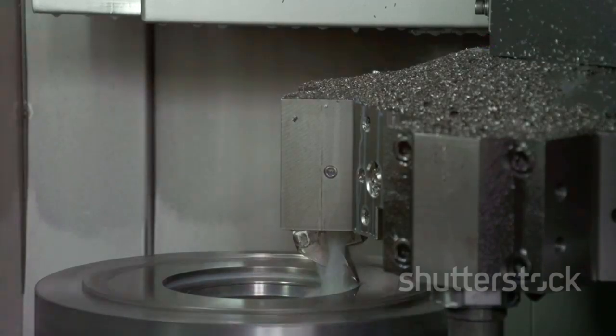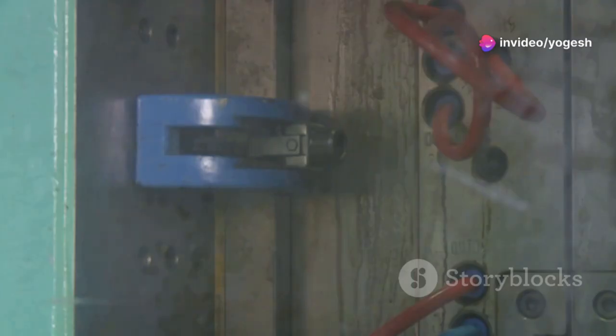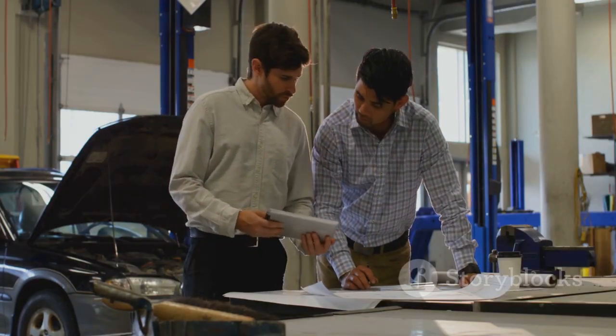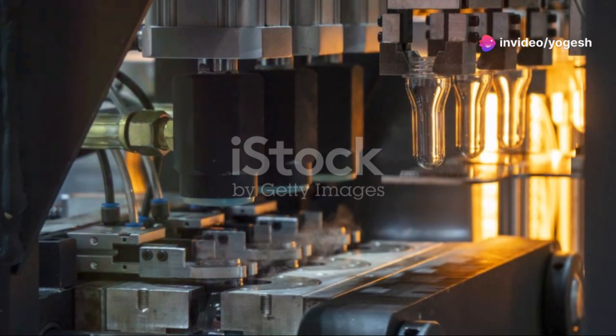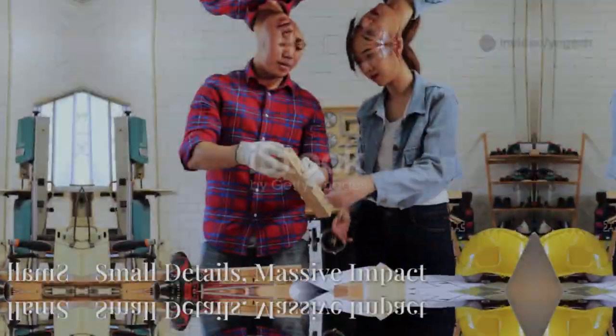Deep parts also need extra draft, even if they're smooth. The longer the wall, the more friction during ejection. Shallow parts can get by with less, but deep buckets or tall enclosures need 3 degrees or more. It's all about balancing design with manufacturing reality. More texture or depth, add more draft. It's a trade-off, but it ensures clean, undamaged parts. Always adjust your draft for texture and depth.